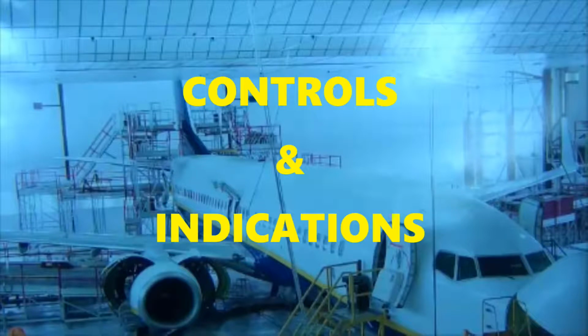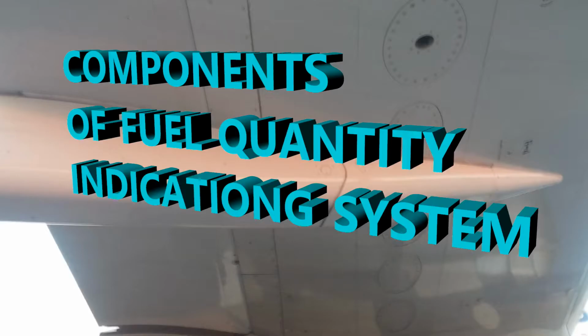Now, what components are involved with the fuel quantity indicating system? You have a pre-selector. I mentioned that in the beginning. There are also fuel probes, because if you see a diagram, there are going to be sensors sensing levels, and when something gets to a certain level. So do we have those sensors? Those fuel probes are part of the fuel quantity indicating system. You also have the densitometers. You've got a computer, and you have a multi-tank indicator.